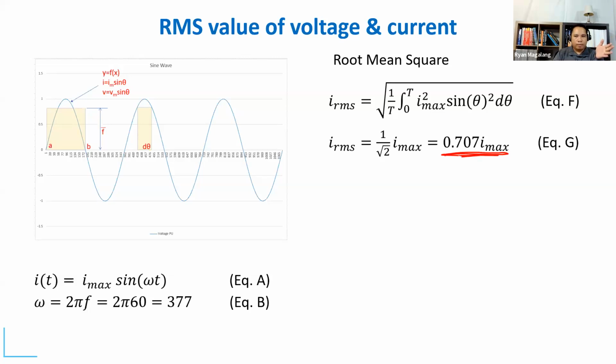But there are cases where you're interested in the peak value of your short circuit current, and that is in what we call the first cycle duty, because in the first cycle the short circuit current tends to be higher because of the DC offset.